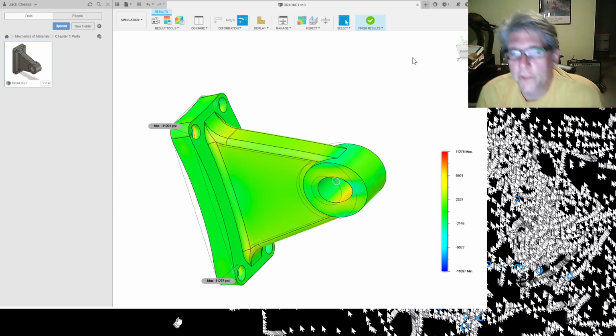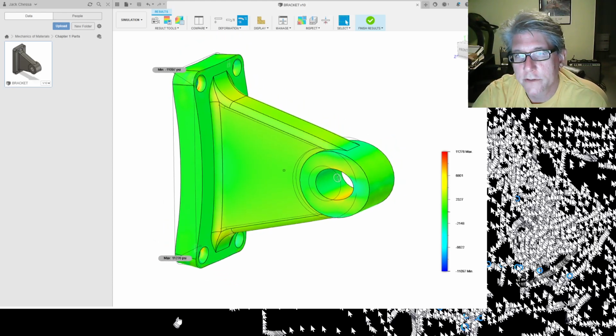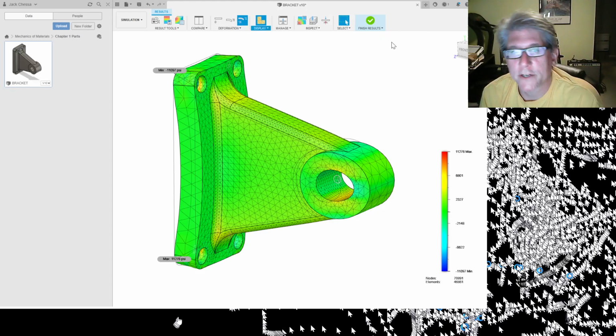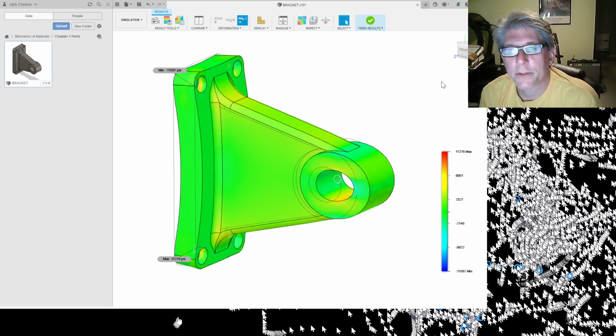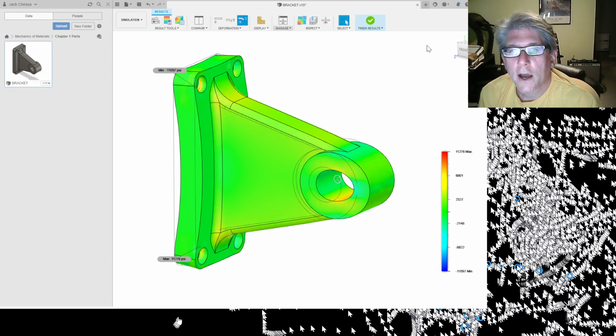But anyway, for this exercise, I wanted you to look at these stresses sort of through cutting planes in here. So we need to be able to generate a cutting plane. So let's do that. You can display it with the mesh if you want to. You can display the undeformed. You know what I mean? Usually we don't put the mesh on, but I would say, oh, no, we do want that at least. That's good. Okay, and then we need to do a cutting plane.